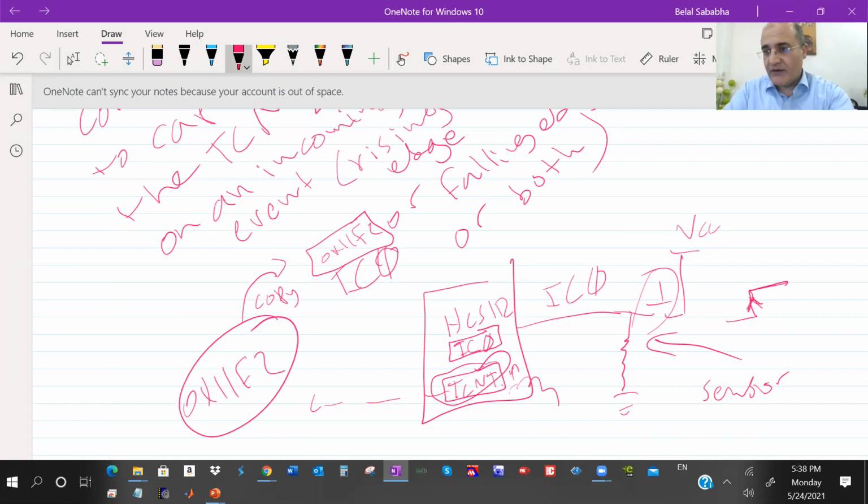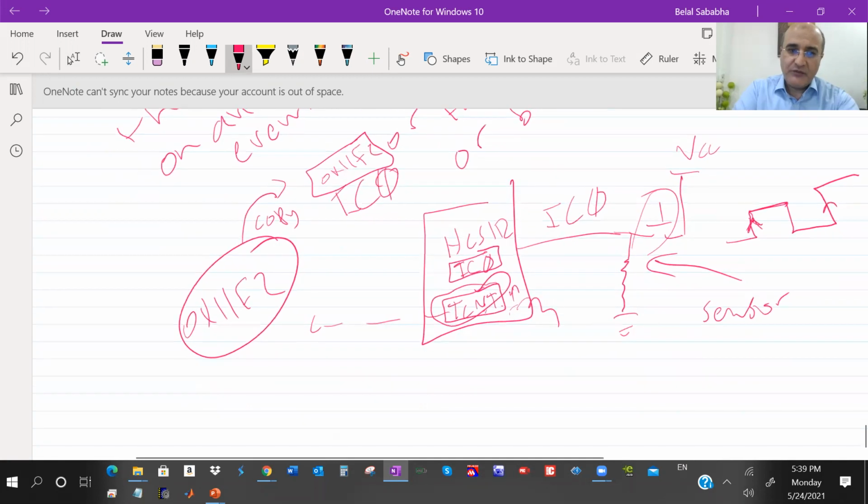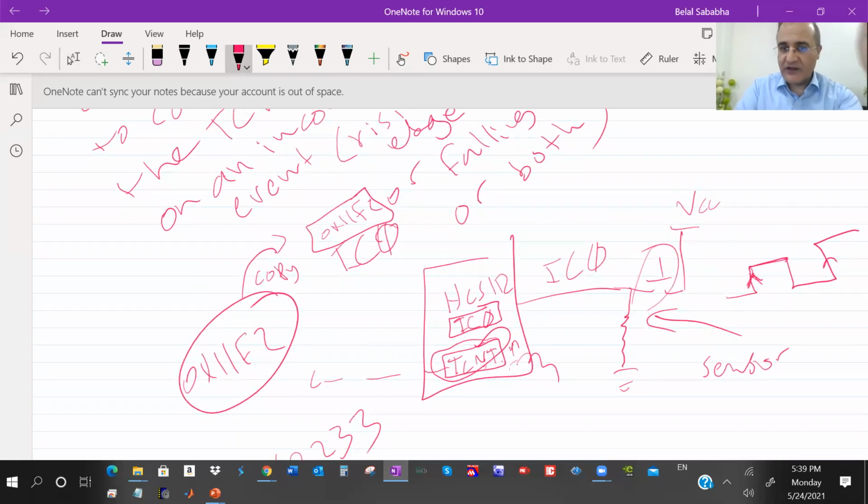So then another input capture, another rising edge, maybe, happens later. You did not change the configuration. This continues counting. Maybe its value became 0x2233. Okay. In the meantime, you can get interrupted or check a flag that the first rising edge came.